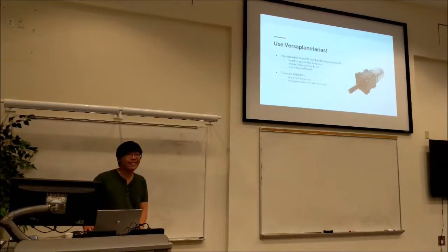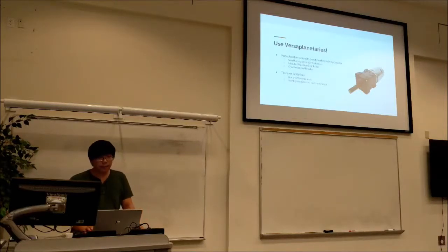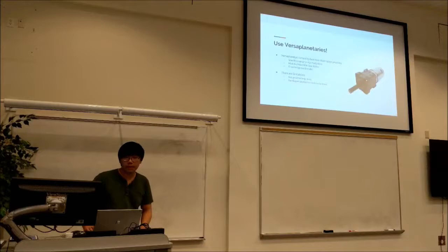One more thing to stress is use VersaPlanetaries, because in terms of custom, it's difficult to beat the packaging of a VersaPlanetary for large reductions, because it uses a planetary gear set. But there are some limitations to the VersaPlanetary in which you would use a custom gearbox instead. For example, it's not great for large loads. Also, there isn't really an elegant solution for multiple motors to be used as input into a VersaPlanetary.